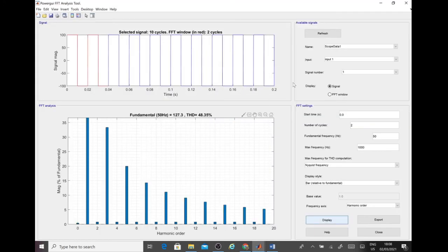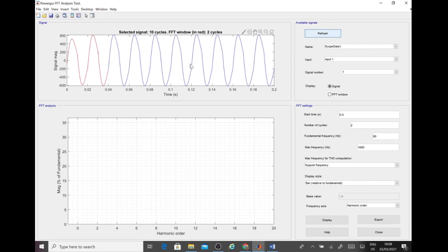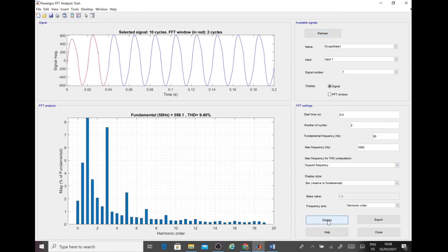Now if we would like to do the Fourier transform, so yes, let's just refresh. Okay, so this is our voltage across the load. And now if we would like to do Fourier, so I guess we need to say draw. And now look at the total harmonic distortion. Total harmonic distortion dropped from around 20 to around 9.4, only 9.4.